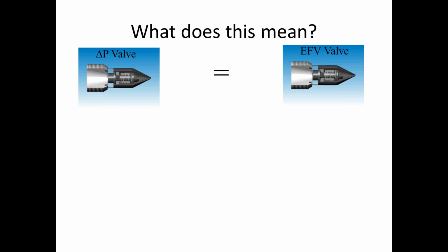Again, what does that mean? Well, in other words, what we have really is a pressure differential valve. It's a valve that understands the pressure differential across it because it's sensing those pressures. And as the pressure changes into the signature that overcomes the forces inside, the valve is going to either close or open back up.